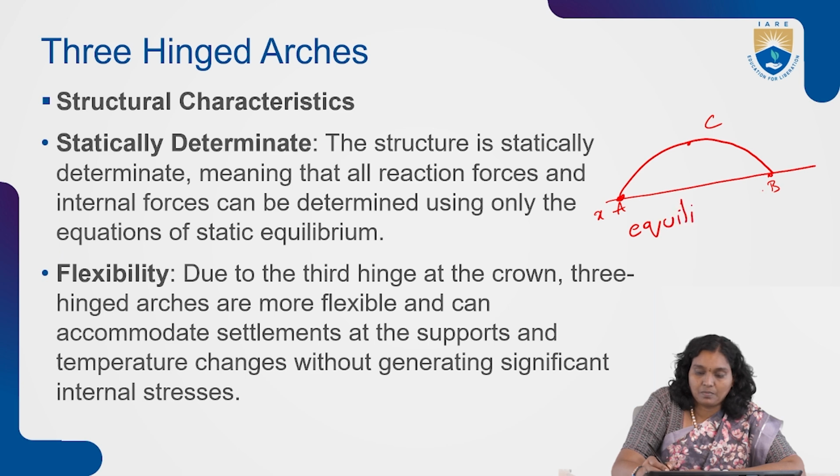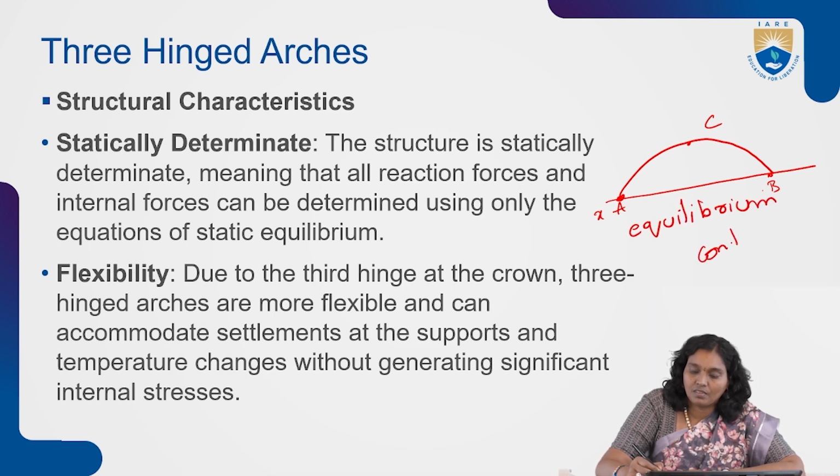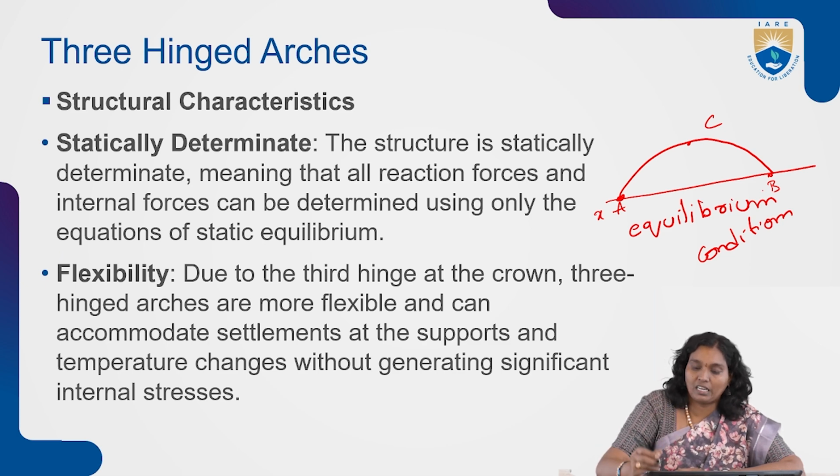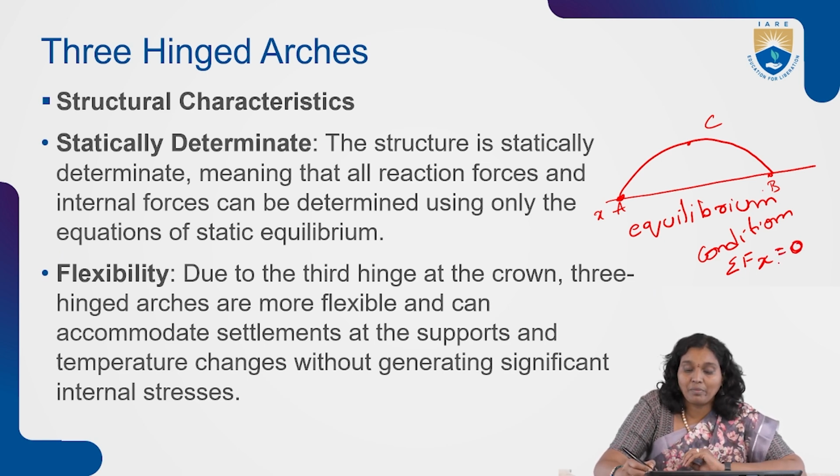Here, whether the structure is statically determinate or indeterminate depends upon the equilibrium conditions. What are the equilibrium equations? The sum of all forces which are relevant to that particular element. Those are the sum of horizontal forces, or in terms of x, we are calling here the x-axis. So, the sum of horizontal forces is equal to 0. This is one of the equilibrium conditions.